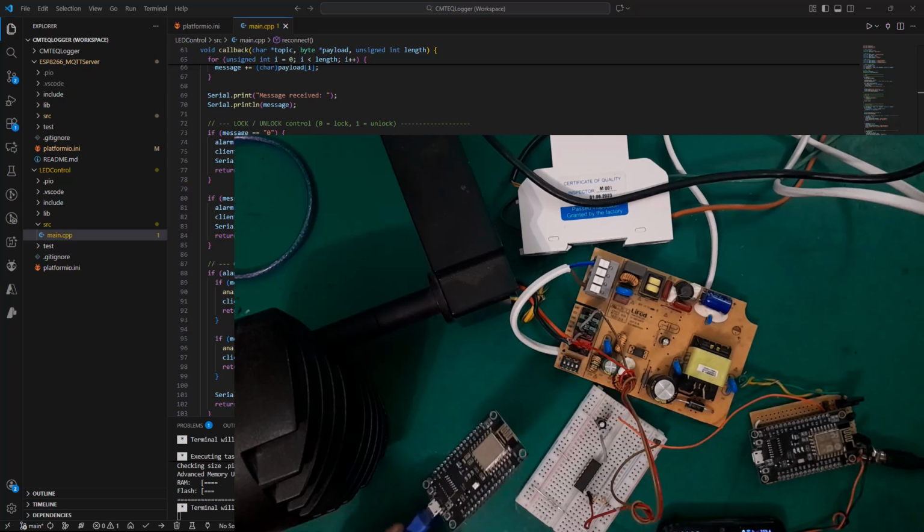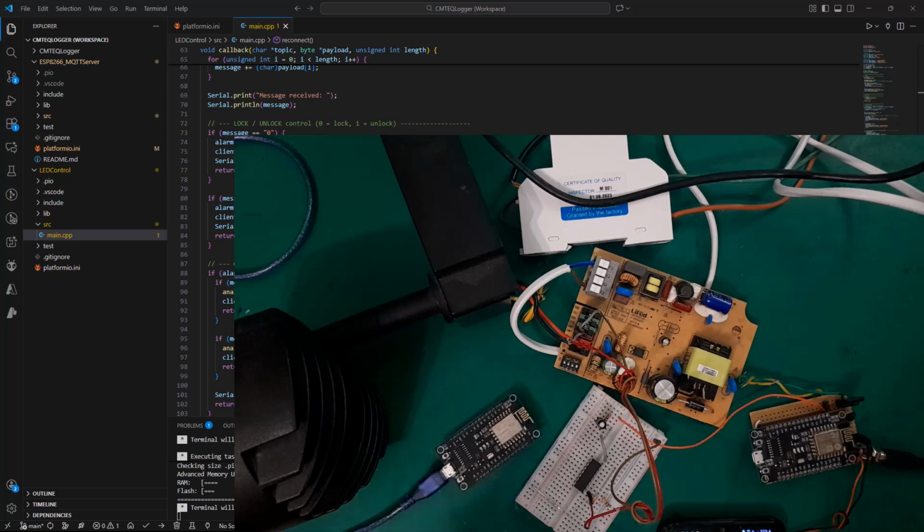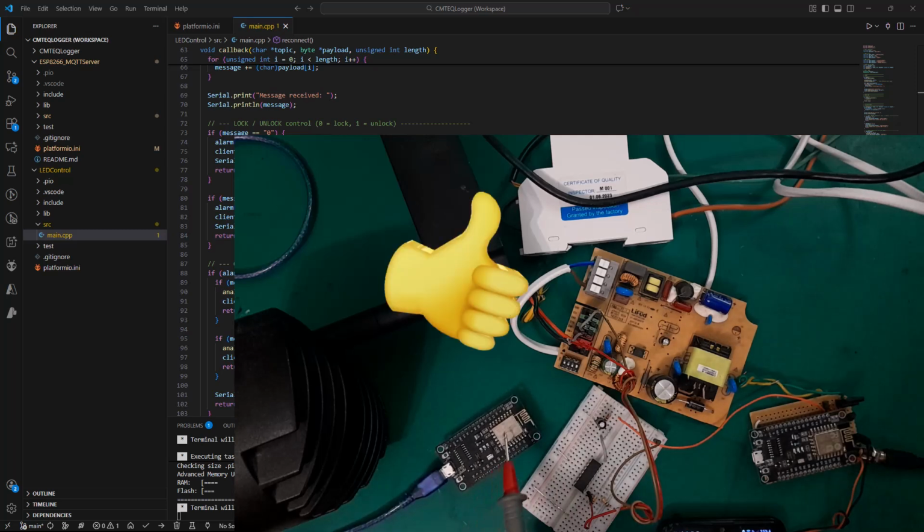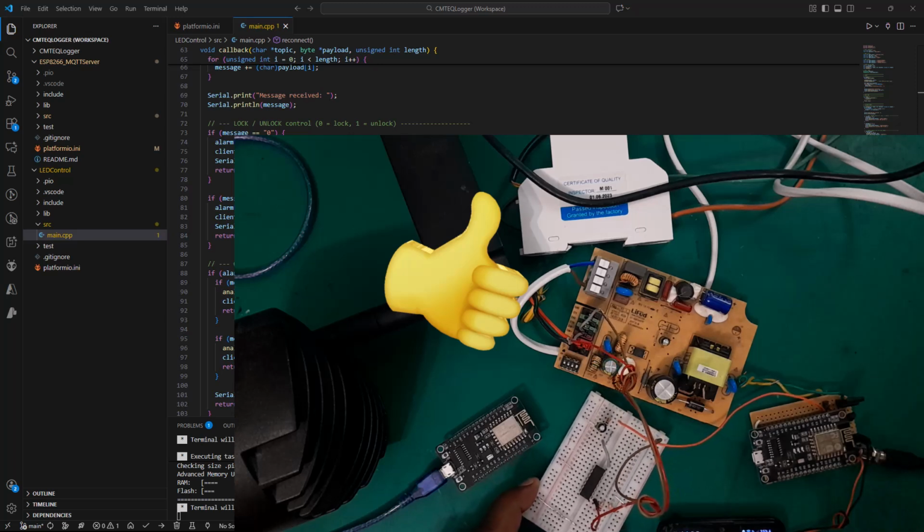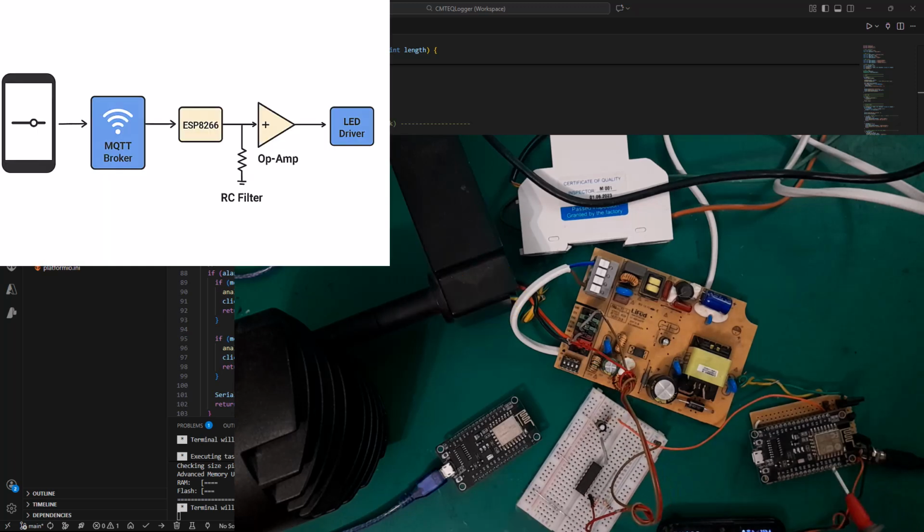So we've got a server here that is running. I also have a tutorial whereby I discuss how you can set up an ESP as an MQTT server, right? So once the server handles our commands, this ESP subscribes to the commands, receives them and sends them over here. Then based on the commands, the ESP is going to execute the control, either to turn on, off, or to control the PWM.